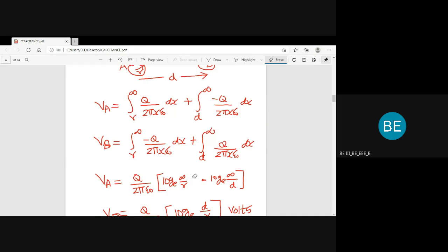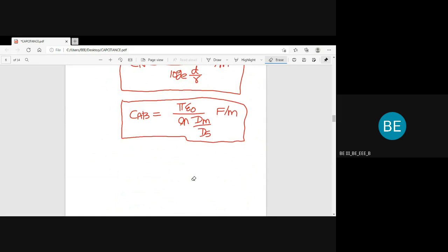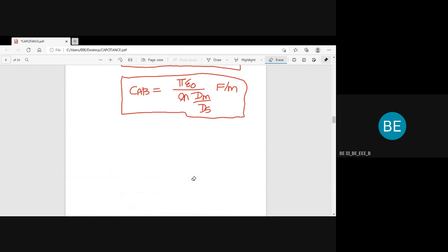Based upon the conductor configuration, it will vary. So for each configuration, we have to find dm and ds as in inductance. The only difference is in finding dm and ds: mutual will be the same for capacitance as well as inductance. So only one change in the ds.